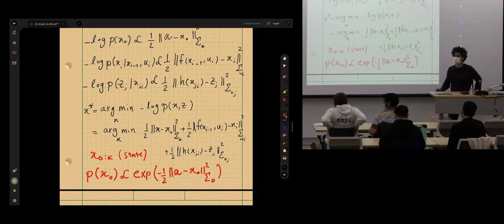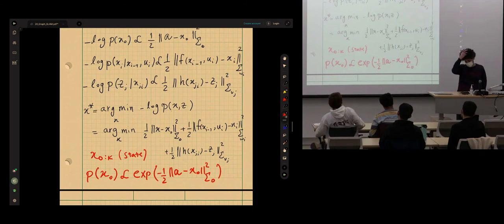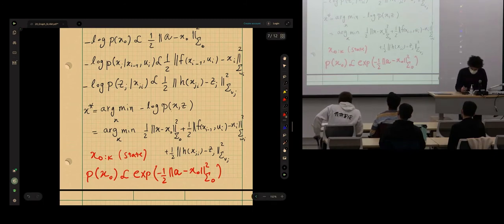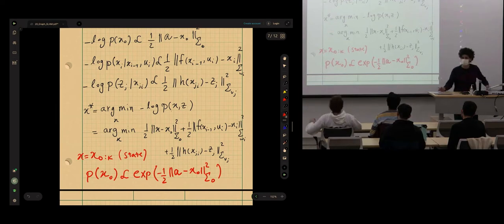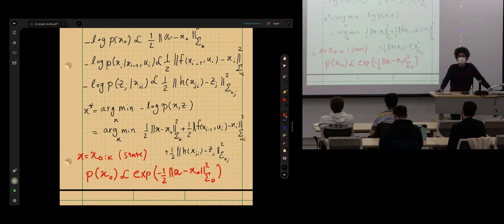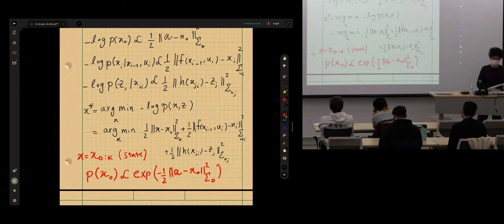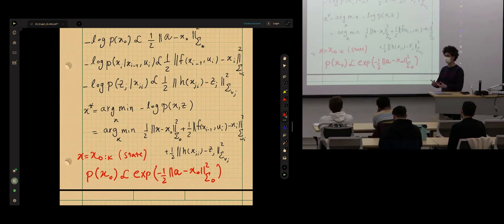Okay, so my question then is, x with no subscripts is the state that we're trying to optimize over, right? Right, x with no subscript was basically the entire trajectory. So the state is the entire trajectory, and by trajectory, I mean it can be at any time step position, orientation, velocity, bias terms, landmarks, anything we want to estimate. And of course, we assume we have enough information to estimate all of that. You can't just arbitrarily add state variables if we don't inject enough information or factors into the graph.